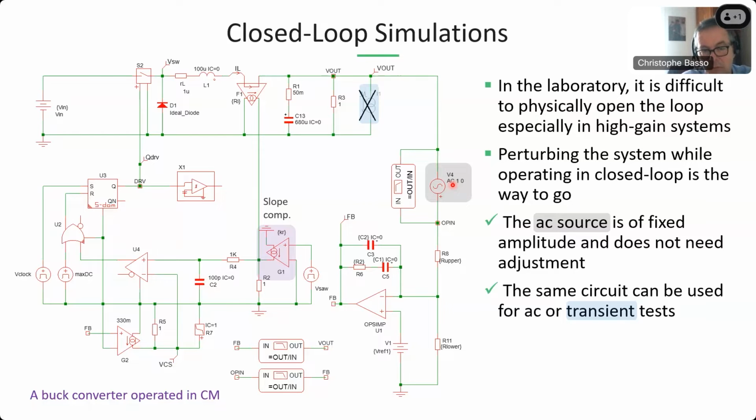And that's the issue. You will need to vigorously inject a low frequency sine wave to make sure that it propagates through the circuit and shows up on the output, so that it can be analyzed and extracted from the switching nodes. However, if you inject too high of an amplitude, of course, you may disturb the power supply, not destroy it, but you have to be careful. It can saturate the circuit, which you don't want. So you have to carefully adjust the amplitude of this modulating source so that you do not saturate the converter.